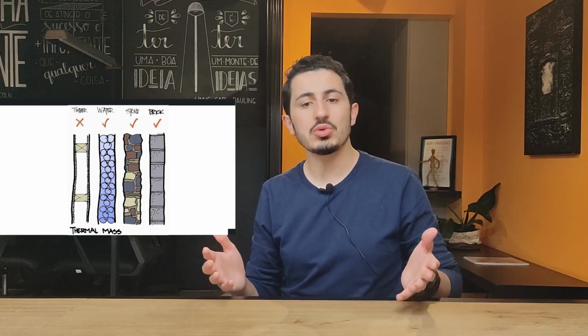When we are in the design phase of the building envelope, the most important thing to consider is choosing the appropriate material. For example, materials such as concrete, brick, and stone have high thermal mass, which means they store and release heat slowly. This feature helps us regulate the interior temperature and reduce the need for mechanical heating and cooling. On the other hand, materials like glass have low thermal mass, which means a building with large glass facades or curtain walls may require additional insulation or shading devices and will use more mechanical heating and cooling.